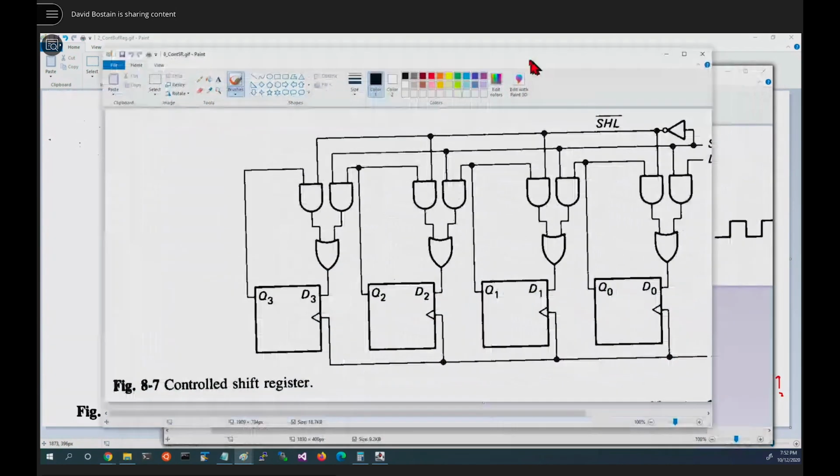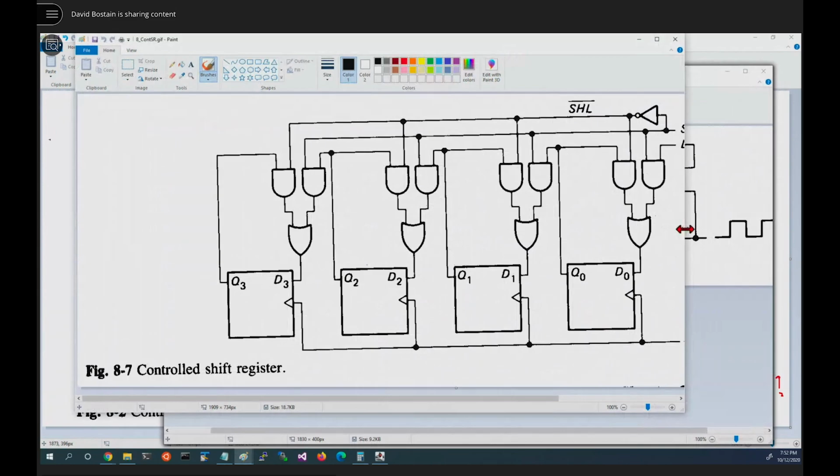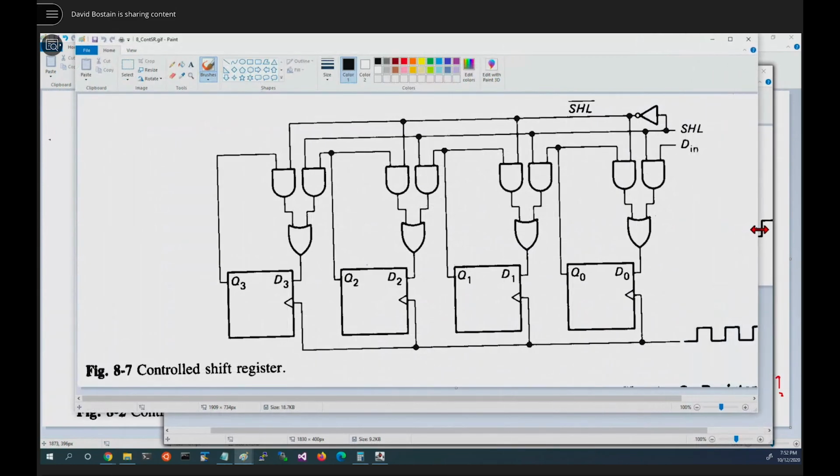A more practical look would look like this. We combine the buffer register notion with the shift left. And we could also make this with a shift right. We could do either. But now what we're doing is we're going to recycle Q. You see Q being recycled into ourself if the leftmost guy is enabled.